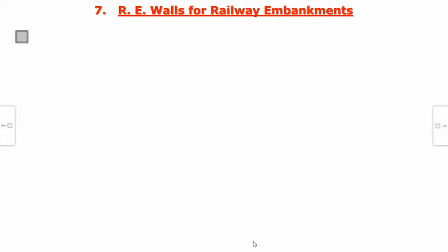So much so, as I told you, we did not do even geotechnical investigation. I was surprised to see in one case, I will not name the zonal railway, where for backfill material and reinforced fill, they say, let us assume a value of C and gamma equal to this. This is horrendous, let me tell you. Can you assume in design the value of that material? And there is a circular which says we must assume this much. Listen, nowhere does it happen like this. Why should we assume? I should go and test it in the lab.